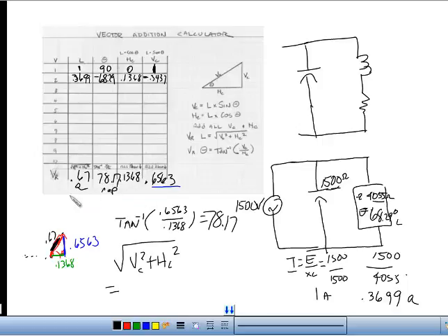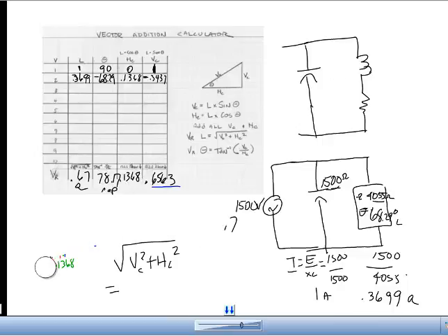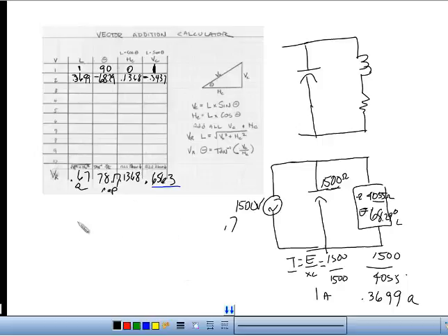Right, so now we found the currents with an assumed voltage, we added the currents with vectors. Final step is this. I'm going to clear a little space, and I'm going to say our final step is going to be impedance is E total over I total.